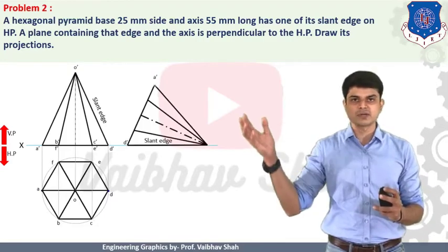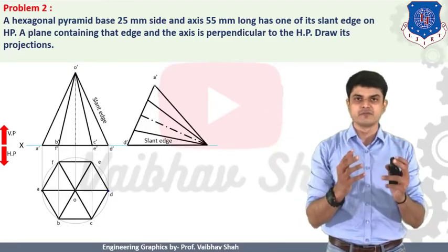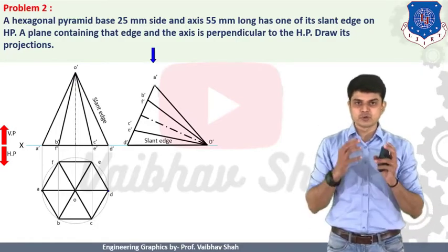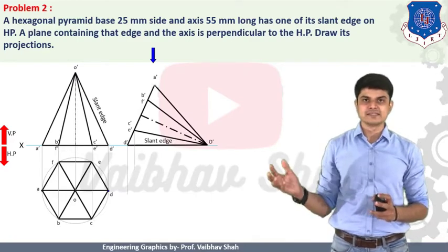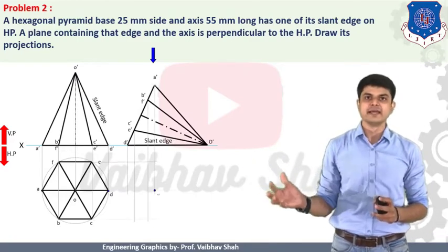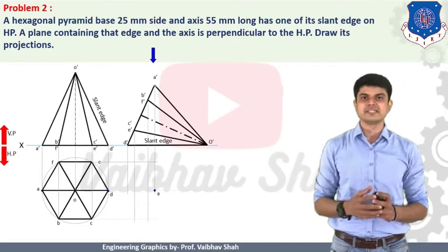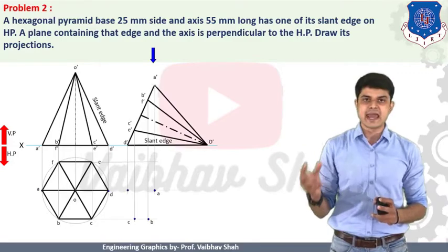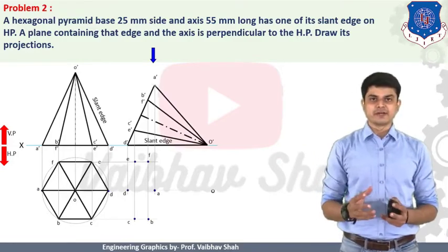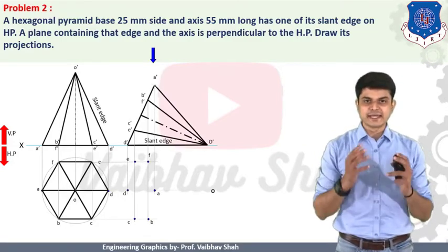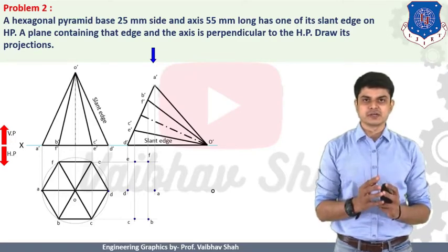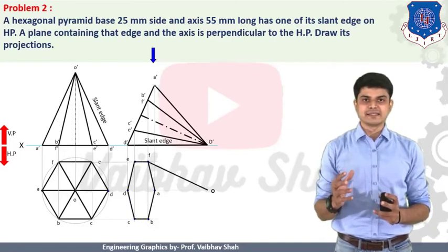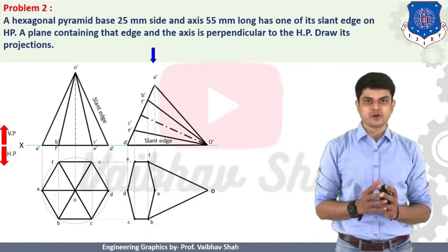Thereafter we will just redraw this figure of the first stage front view like this under the resting condition. It is very easy. After that we should draw the vertical lines from each and every point like this. So we should draw vertical lines from each and every point, and thereafter we should have the horizontal line from each and every point in order to define your points A, B, C, D, E, and F. Thereafter we should define the point O like this. So now after getting each of the points, we should first construct the periphery of the object. So first construct the base of the object like this, and then after construct the outer periphery of the object.